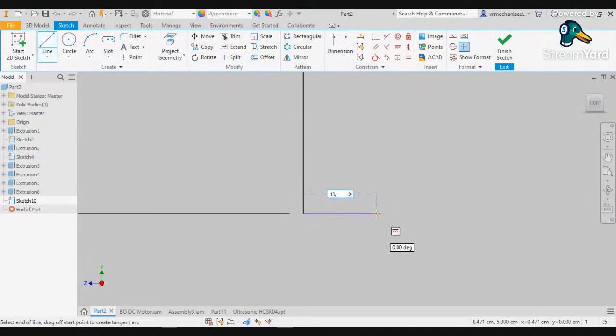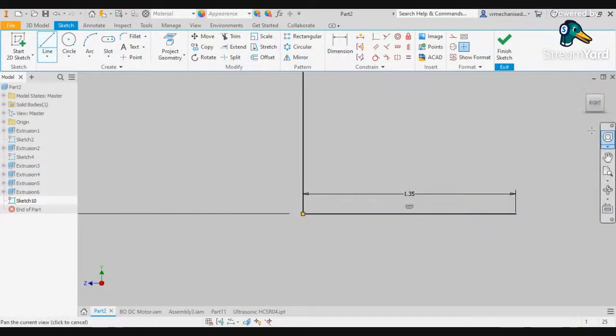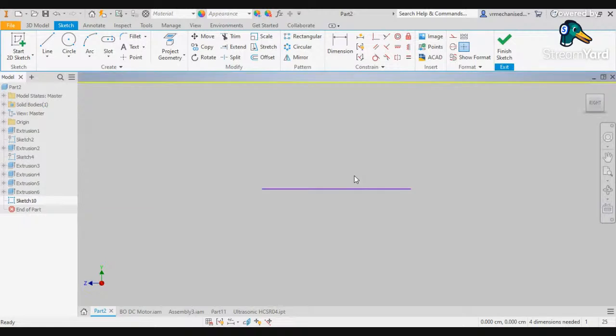It's drawn, and from there we'll be directly drawing it as 27 mm, 2.7 centimeters. We have got it. So now delete the extra constraints over here. Delete the extra line, delete the support line, and now we'll be drawing the circles.